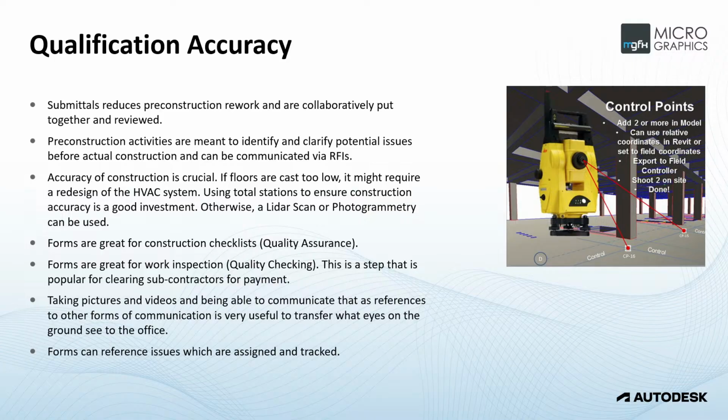Now, you can never be perfect, but we strive to be, and there are solutions that you can employ in this regard, which includes things like point layout, but also laser scans, LiDAR, as well as photogrammetry. And quite often also, if we do want to do record modeling, then that can happen on site. But from a qualification perspective, just scanning before pouring and understanding exactly if we are going to be constructing accurately is very important. The more accurately you manufacture a building, the less rework you have to do, and the less money is wasted.